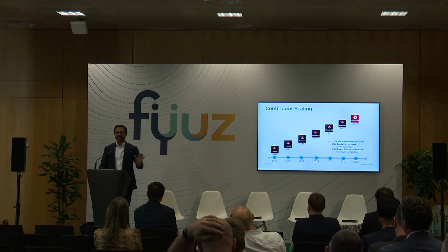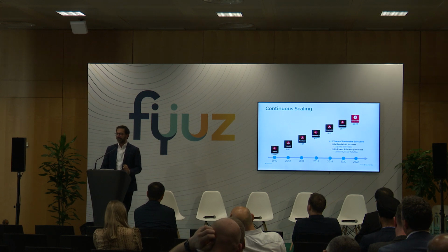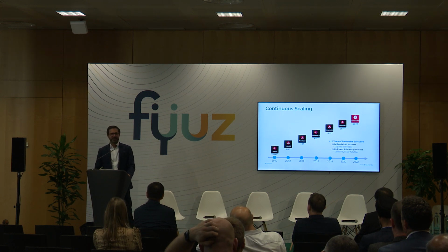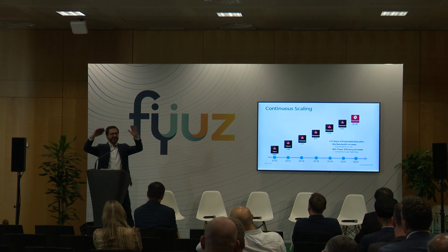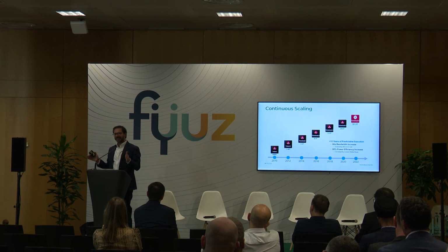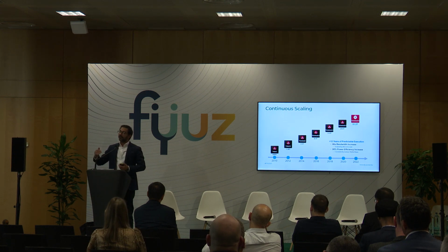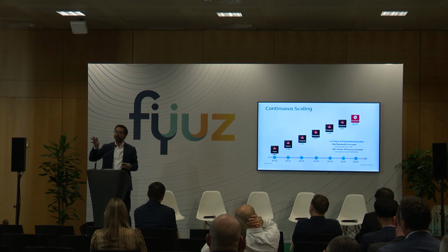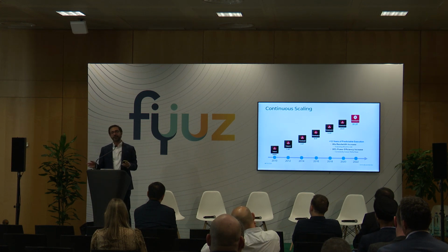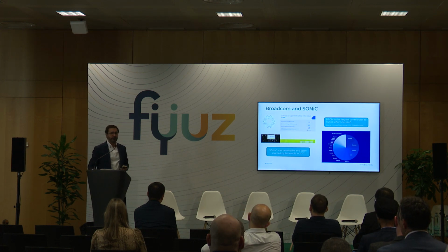Think about it. Even 5 or 6 years ago, if you went out to buy a 128 port, 100 gig switch, you would be buying a multi-chip and a modular chassis, a complex system. Today, you can get all of that in literally a pizza box size form factor. That is the benefit of having efficient silicon. Your hardware becomes much simpler. And when hardware becomes simpler, writing software, a network operating system, becomes very simple as well. That is why you see there is a plethora of open source network operating systems out there.